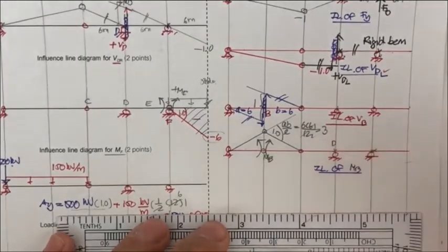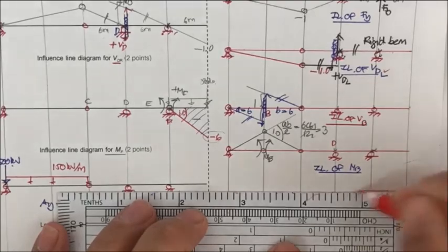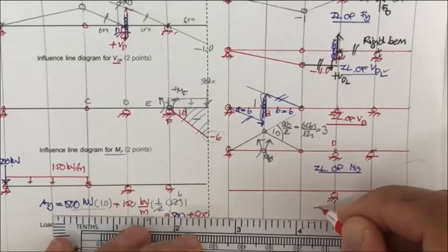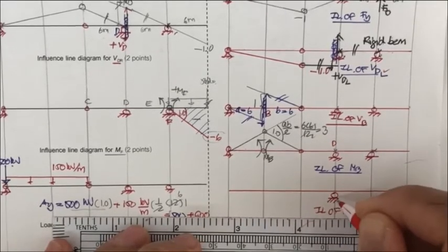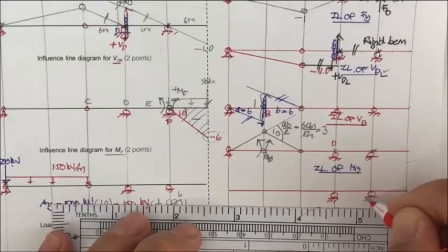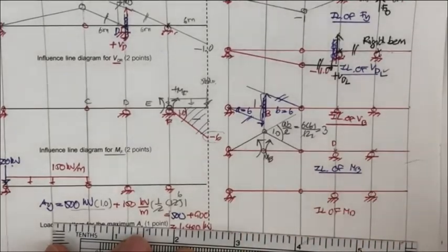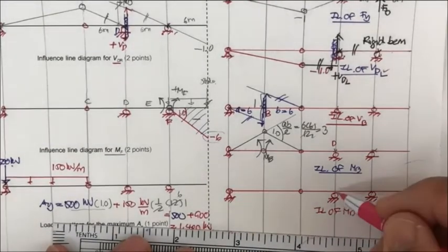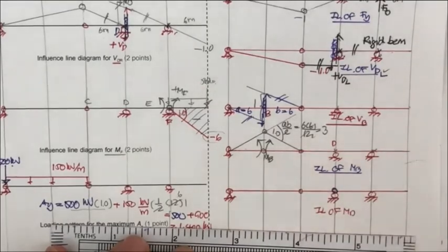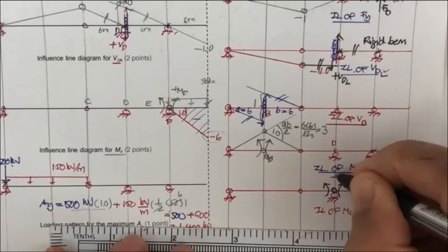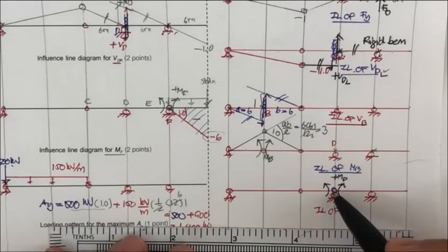D is here, this is D. You're going to draw the influence line of M sub D. D is here, this is F. This is the hinge, this is the pin. What you do is eliminate the resistance by putting the hinge at D, and then you put the positive moment M sub D, and this one has two-side support, no movement.